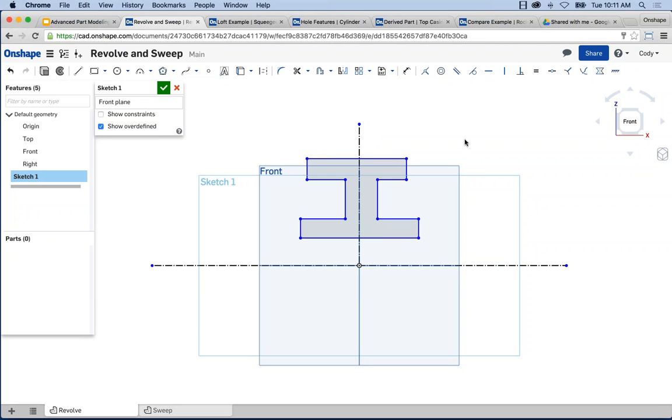Now to do this, we'll create what's called a symmetric constraint. So I'll select point, line, point, and choose symmetric. The key thing here is now this line is centered around that construction line. So it will remain centered no matter what dimension I change this to. I need to do this in a few places. Again, point, construction line, point, symmetric. And this will give me that centered behavior that I'd expect. So as I drag this now, it behaves with symmetry.